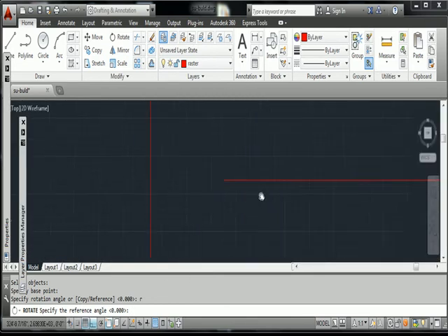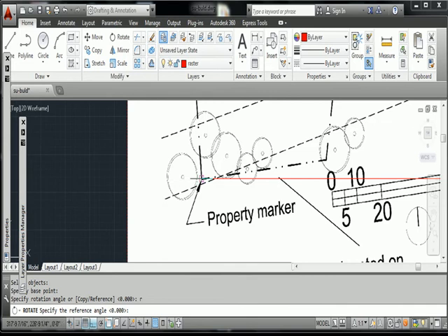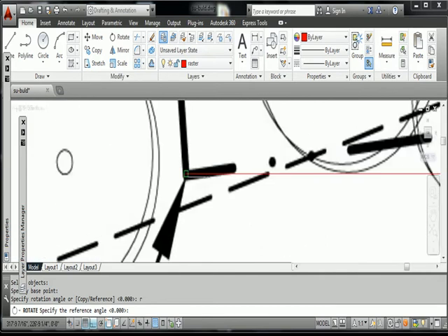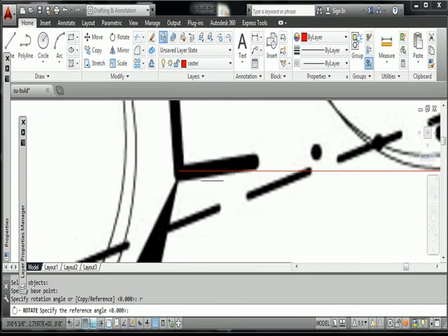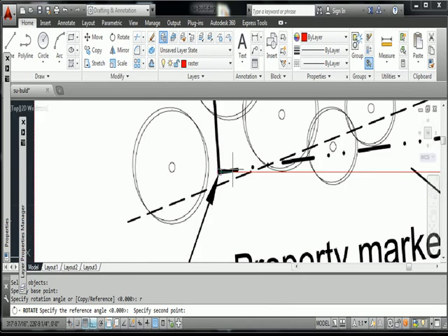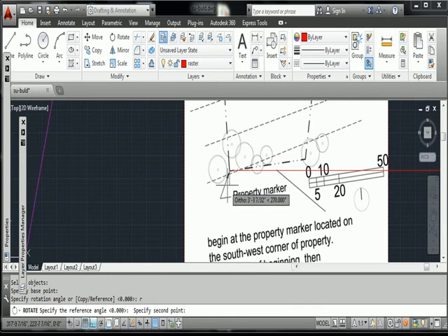What I then need to do is specify this line, and I do that graphically again by selecting that first base point, that first point that I got to, and I have this line to help me out as I select just at that point. And then, when I click on that, the next thing AutoCAD asks me is to specify the reference angle.